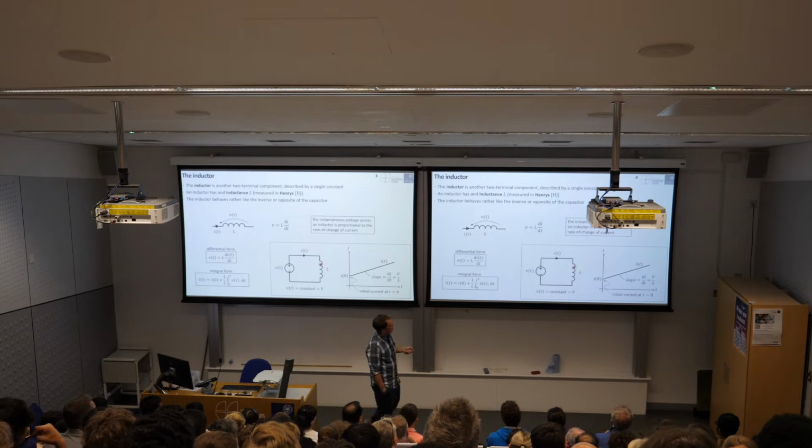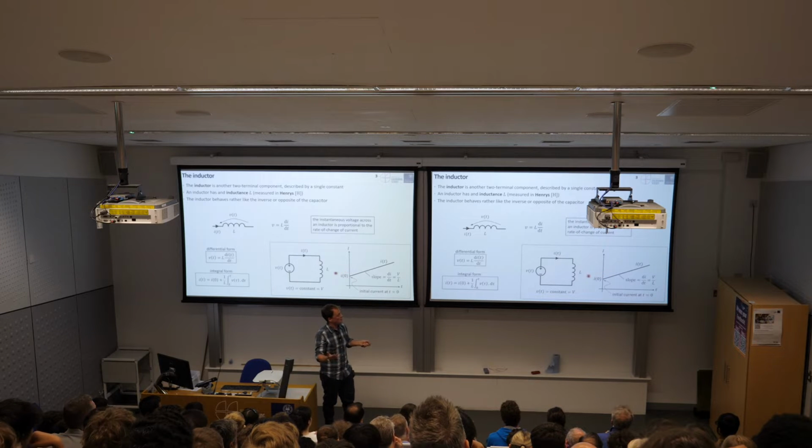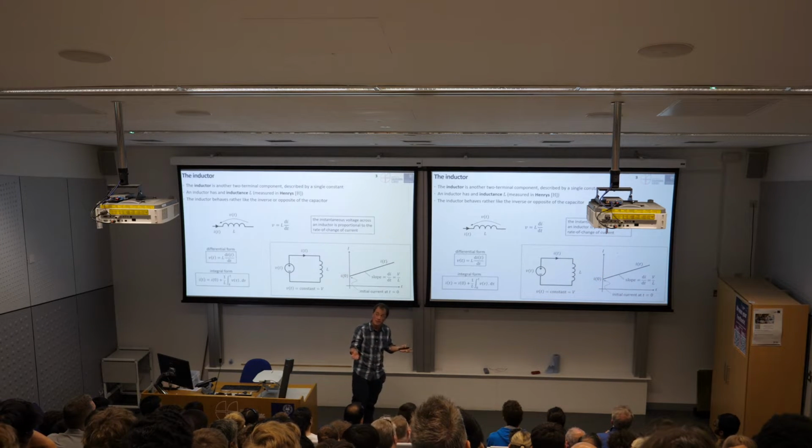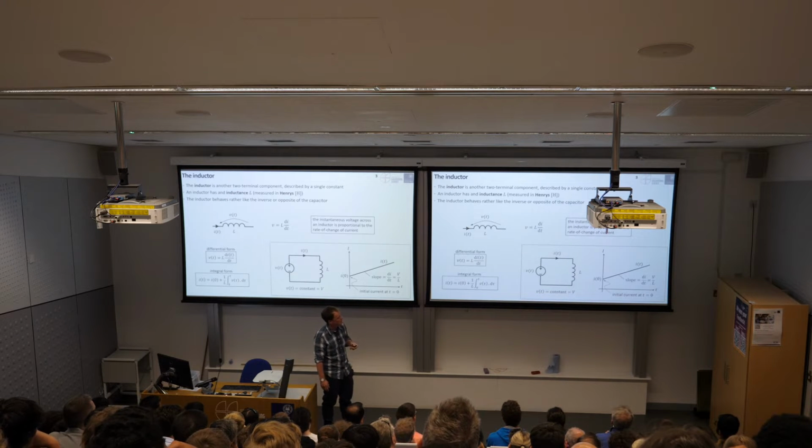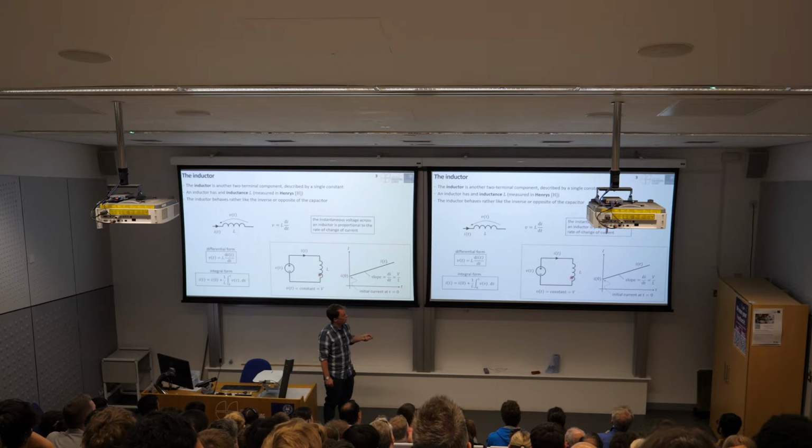So what happens is I start the circuit up at time 0, and let's, for the sake of argument, say that maybe there was a current flowing initially. It doesn't have to be 0. So we've got a current at time 0, and then I apply this voltage. Because I'm applying a constant voltage across the inductor, and the inductance is constant, di/dt must be a constant.